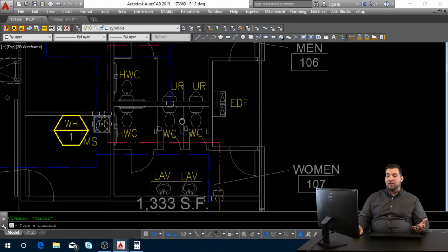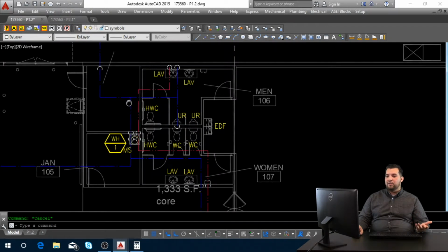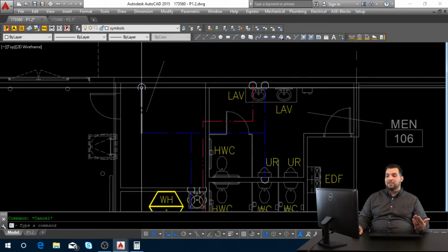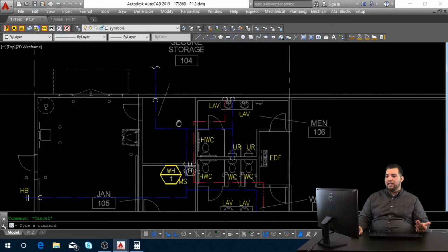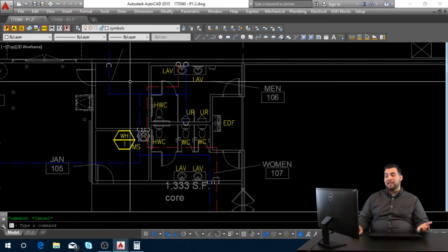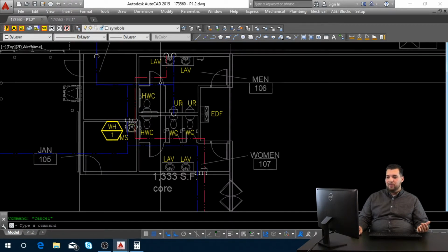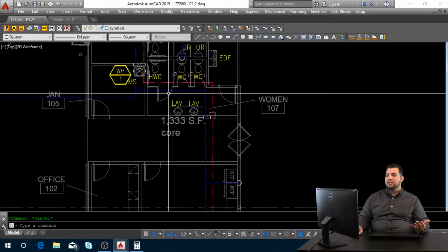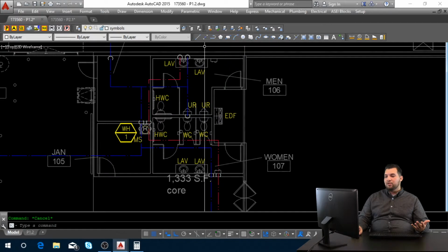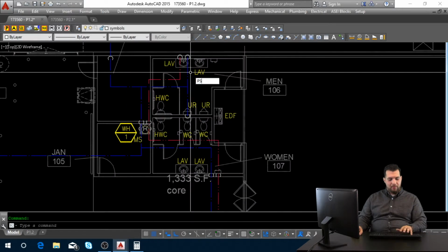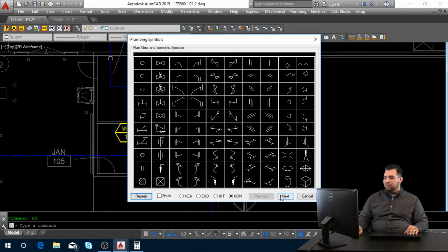You want to go ahead and provide shutoff valves for wherever you need. Here, on the riser, we're going to provide a shutoff valve in the riser. So once we do that, run it out. I'm going to go ahead and specify that with our keynotes as well. So if you do need to show it, for example, this water line goes directly to our group of bathrooms, so we might want to just show a shutoff valve for this size right here.